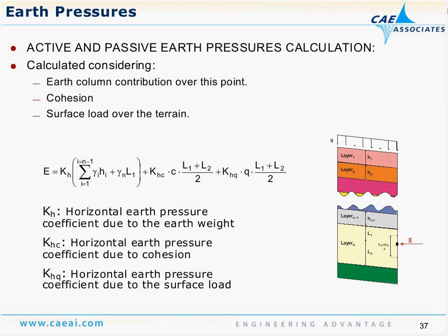And the earth pressures can provide you not only with the vertical, but also the horizontal, based on the equations that you might find in most geotechnical handbooks, where they sum up the definition of the layers and the densities and come up with the cohesion levels and calculate the equivalent lateral load to be applied to the model.